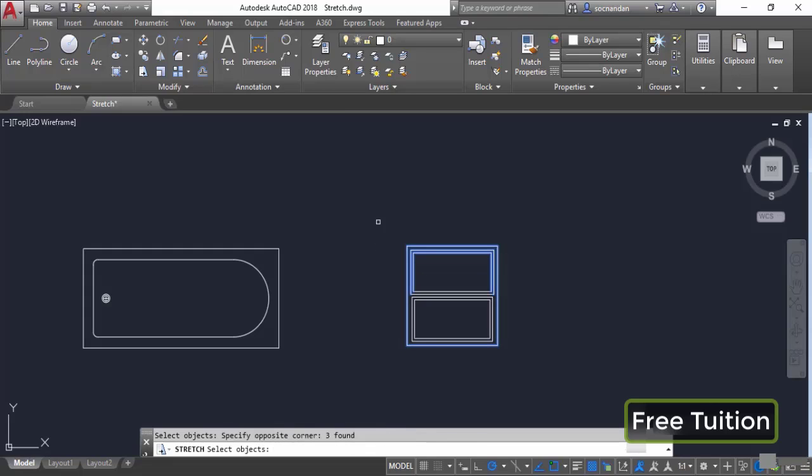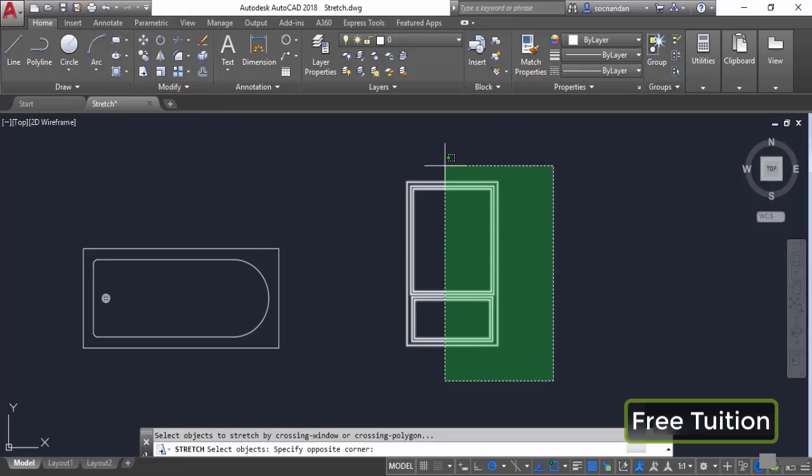So let's click, press enter, click at a point, and now move upwards, and you'll notice that only the 6 line segments which were partially inside and partially outside have changed their length, and rest of the geometry remain completely unchanged. Now let's assume that we want to change its length even further, and we want to increase its length in horizontal direction. For that I'll select this stretch tool, click at a point here, make this window like this, and obviously now you understand that which part will be affected.